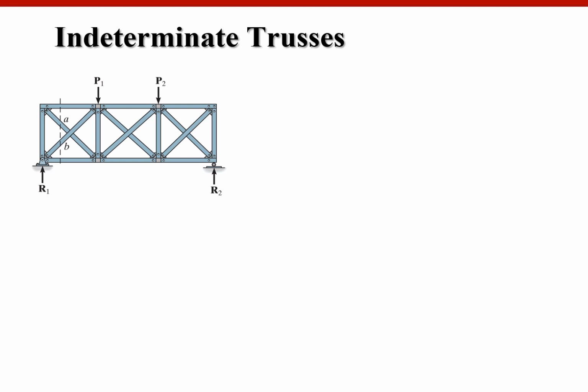All right, and of course, to analyze any truss, whether it is determinate truss or indeterminate truss, we are going to get the reaction first. And then we are going to cut wherever you need to calculate the member forces. For example, we want to know this member force, and this and this. Then we need to cut it there like this. So wherever you cut your member, there is member forces.